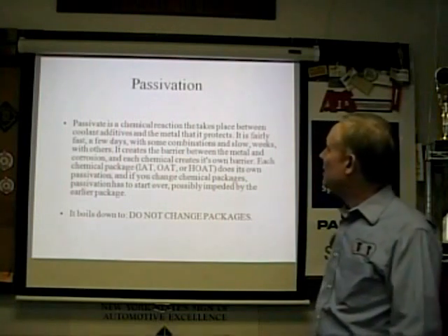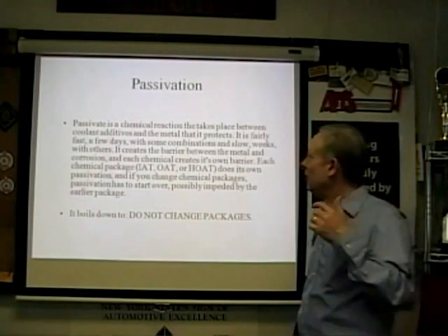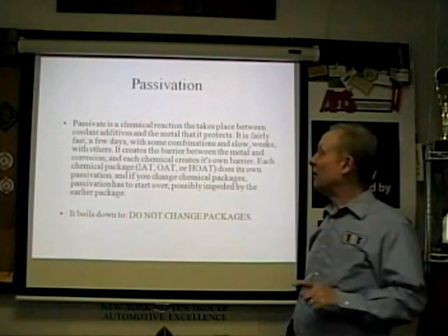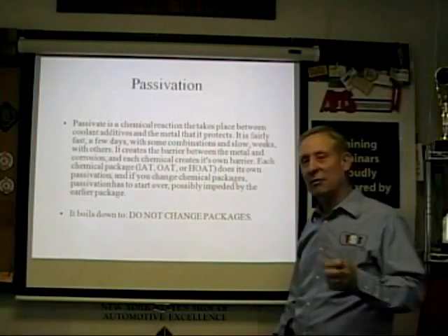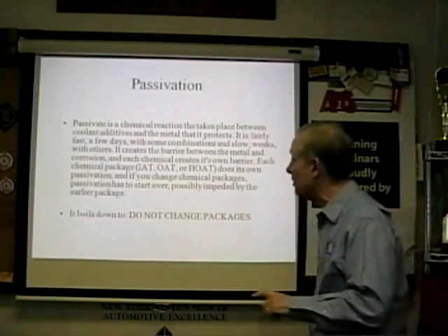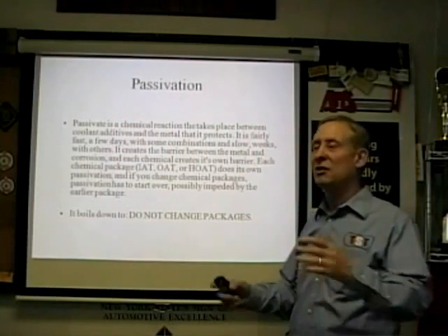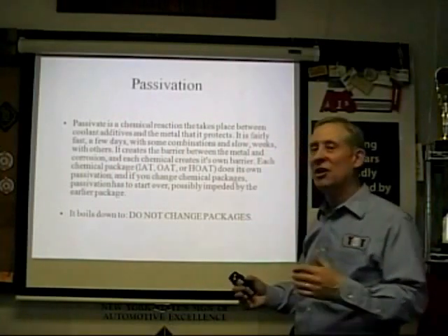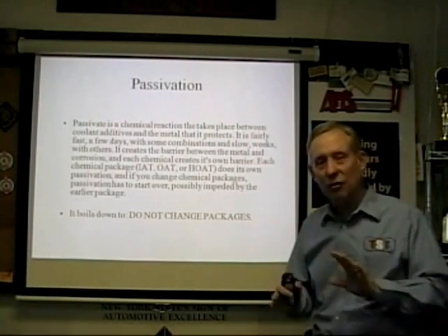Okay. Passivation. I think I said that wrong. I always say that wrong. The bottom line is it's a chemical reaction that's part of the chemistry of the coolant. It's part of why you don't want to mix coolant. The coolant treats the metal surfaces inside that engine to slow down the corrosion process.